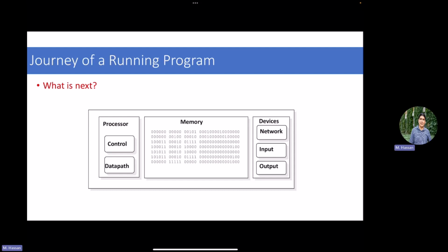So remember that these things are coming from software, right? Like I wrote my C code, the compilers generate them, and then I have the binary file, then I load it to the memory. So these things are already generated completely in the software layer, regardless of what your target hardware is, right? Only there is one contract that you maintain when you do this. It's regardless of your hardware details, except the fact that you assume I'm targeting a certain instruction set. So if this is, for example, a RISC MIPS instruction set, then you know that my instruction is 32 bits. And the back end of the compiler, the assembler, when it generates this binary file, will create 32 bits that represent this instruction, right?